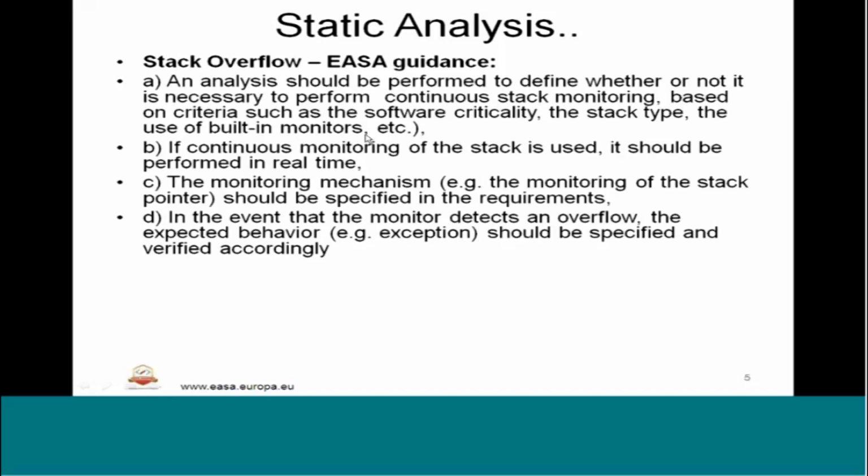See, what will happen is typical embedded software in the airlines industry or aerospace programs will have monitoring functions. That monitoring function also will have stack monitoring functions, and if it finds stack errors, there will be a definite recovery in terms of a reset or reporting, whatever it could be, if it is reaching beyond a certain limit. So that should be analyzed. So that is what it means.